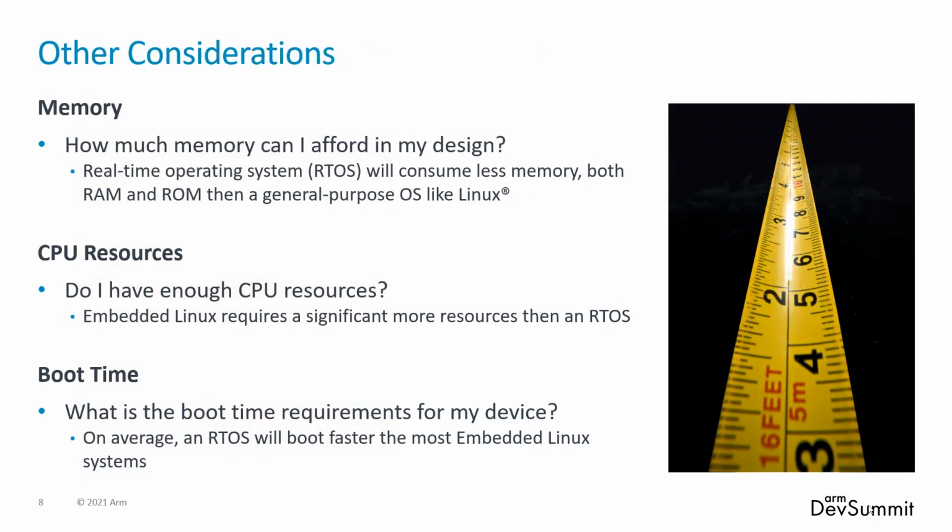And then other considerations beyond that, right? Memory: how much memory do I have on here? CPU resources. For all of these different areas, can I use a certain operating system for that cluster of areas? Boot time: maybe I have a hard boot time requirement as well. So there are things that I need to understand. It goes beyond just thinking about the hardware, to your traditional embedded concerns, both from a real-time perspective and a constraints perspective, be it memory or CPU resources.